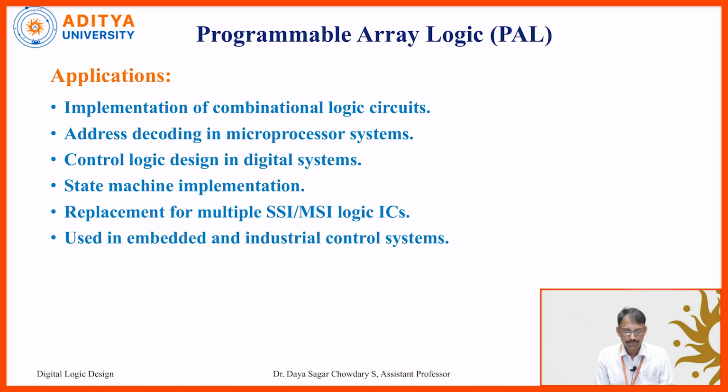And coming to the application part: implementation of combinational logic circuits. Combinational logic circuits can be easily implemented on PALs. Address decoding in microprocessor systems, control logic design in digital systems, state machine implementation, and replacement for multiple SSI, MSI logic ICs. In ICs also we can use this PAL concept. Used in embedded and industrial control systems. So mostly this is for the control system part, we can use PALs for industrial purposes.